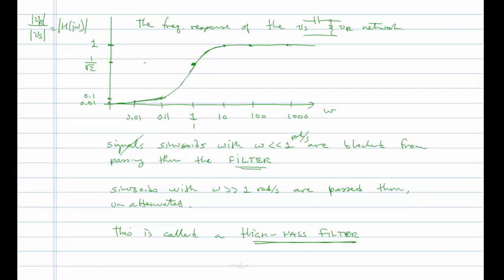And this is really your first view of this whole notion of doing frequency response analysis. I told you that this whole concept of impedance will open the doorway for us to be able to look at the circuits in a different light. Instead of studying their responses as a function of time, we can study their responses as a function of the frequency at which we excite them.